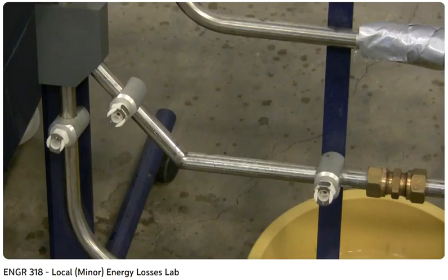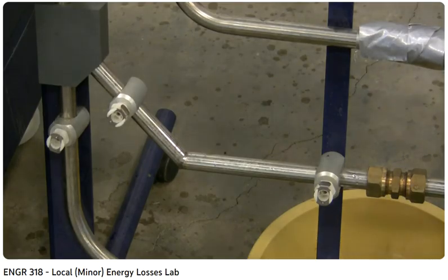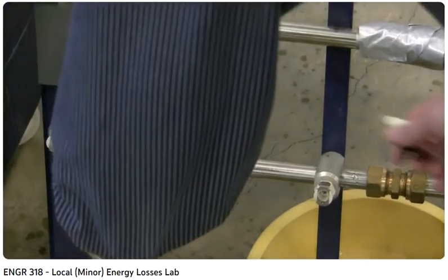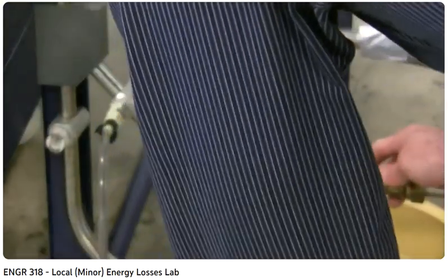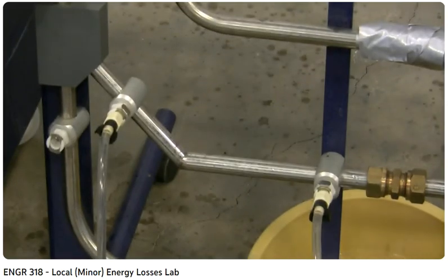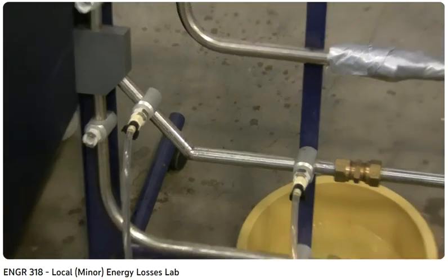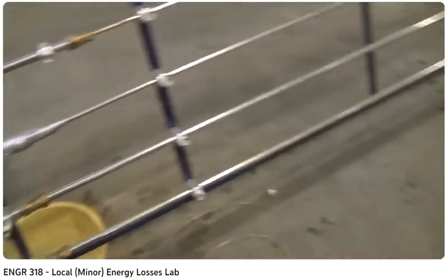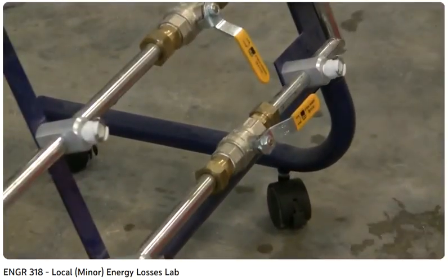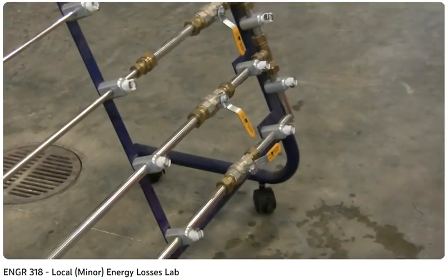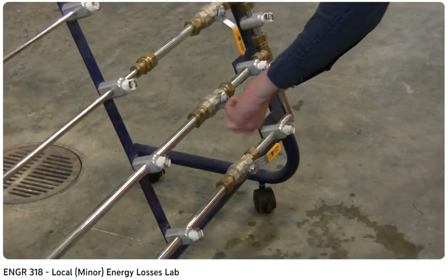The first of the fittings that we're going to characterize pressure loss through here on pipe path B is the 45-degree elbow. I'll connect the taps. Now, I'm going to have to quantify the flow rate again because I've got a different flow path. I previously have been using that valve on the lower pipe. Now I'm going to open up the valve above it. This is open.